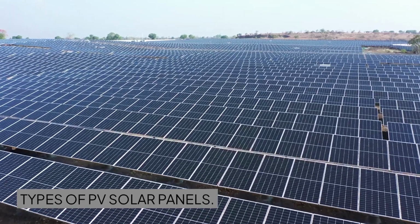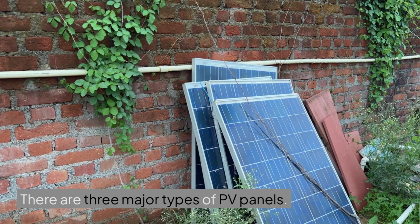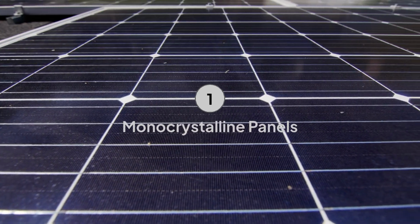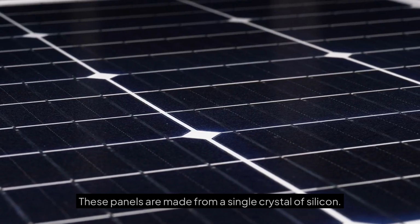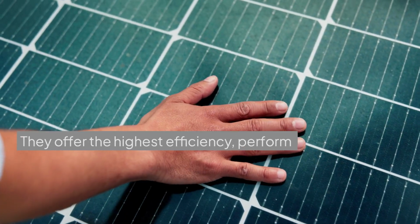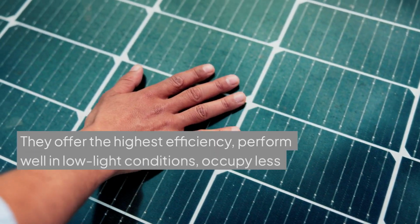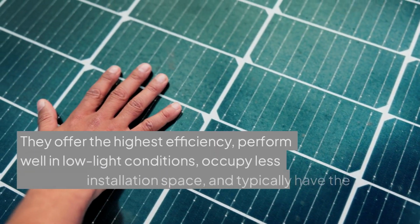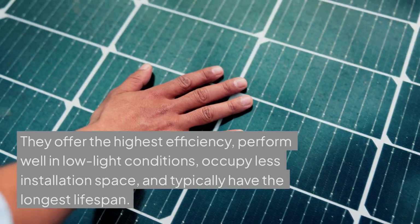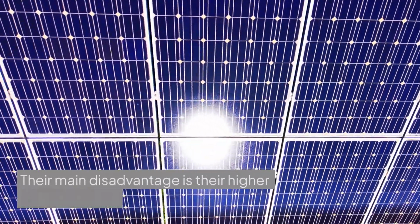Types of PV solar panels. There are three major types of PV panels. Monocrystalline panels. These panels are made from a single crystal of silicon. They offer the highest efficiency, perform well in low light conditions, occupy less installation space, and typically have the longest lifespan. Their main disadvantage is their higher purchase cost.